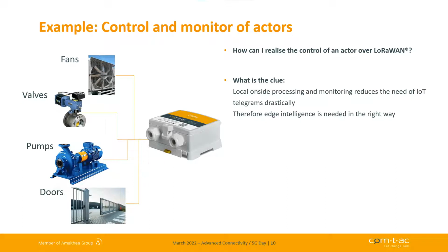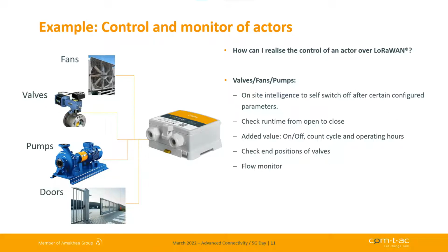We can use that device to control vents, valves, pumps, or even complete doors, because we implemented edge intelligence on the device itself, which makes some pre-calculations. For example, if you want to control a door, it stops by the device itself and does not wait for a message from the network.